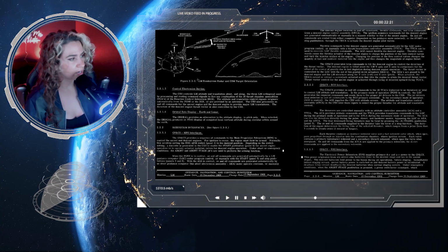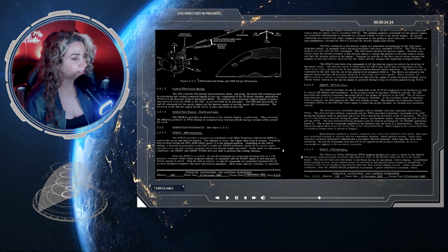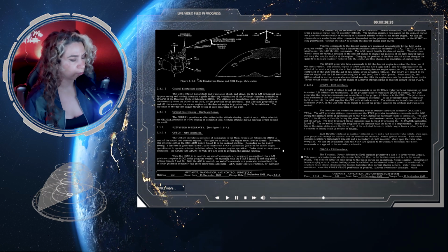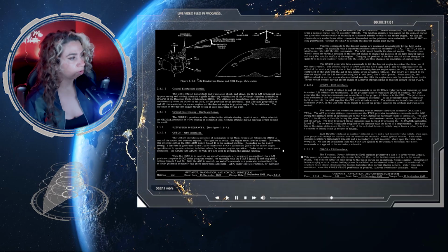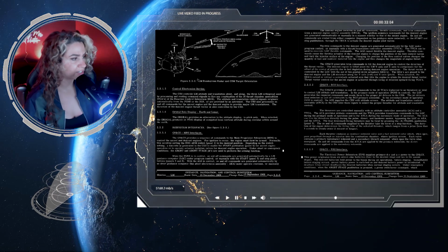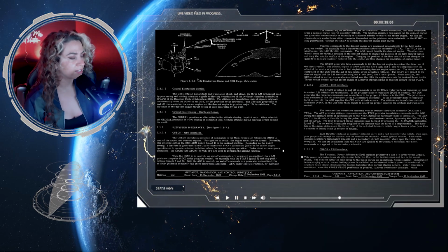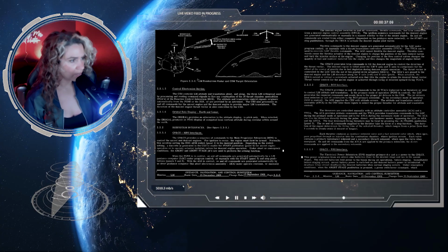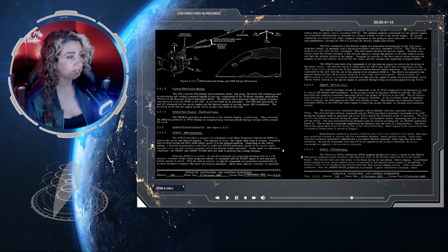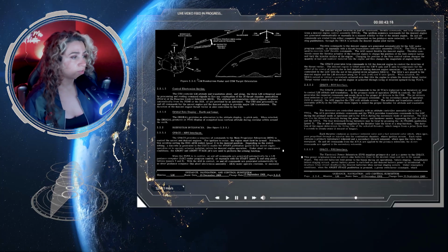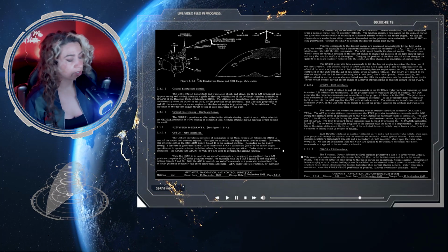Depending on the switch setting, a discrete is generated in the CES to enable the start push button, panel 5, for ascent engine operation or to operate actuator isolation valves for the descent engine operation. Under abort or emergency conditions, the abort and abort stage PBs are used to perform the arming function.